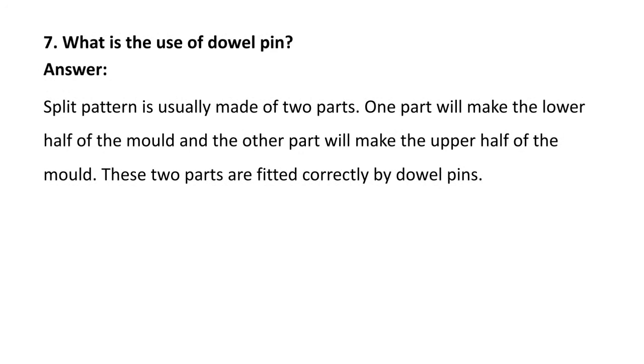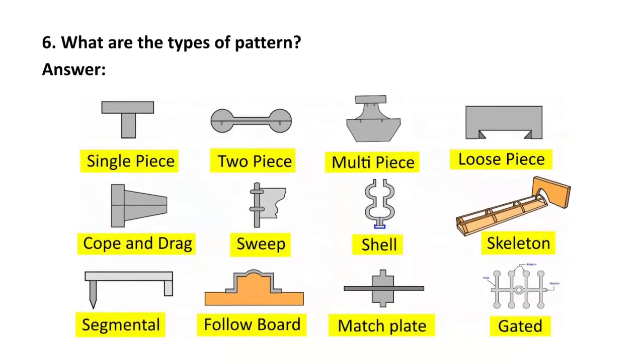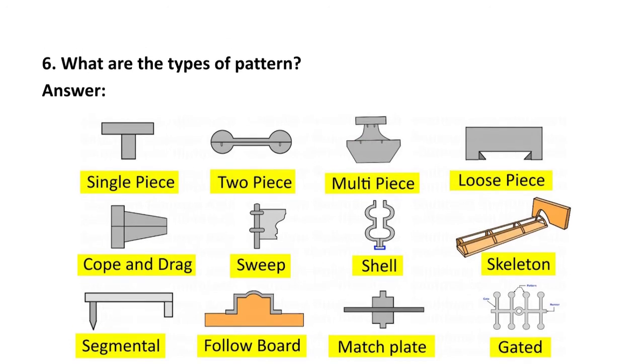Next question, what is the use of dowel pin? So first of all we will see what is the dowel pin. Here you can see this pattern is made into two pieces and they are attached together with the help of this pin. So here you can see the pins. Here also you can see the pins. So that is known as dowel pin.